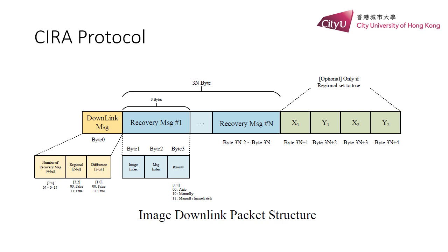For priority, because by the TTN policy, uplinks need to fulfill certain intervals. In our case, it is 8.9 minutes. So we need to wait around 2.5 hours to get a downlink. However, the user may want to send the downlink immediately instead of waiting 2.5 hours.